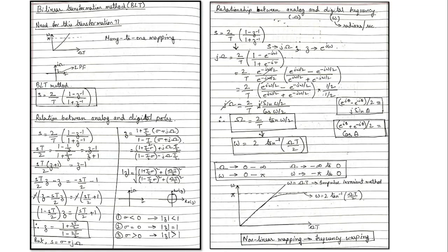So this resulted in aliasing, and that is undesirable. To overcome such undesirability, we discussed that there is a need for band limiting the signal before we can process the signal using the digital filter that has been designed using the impulse invariant method.